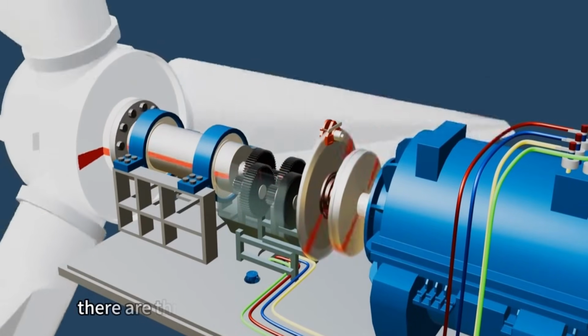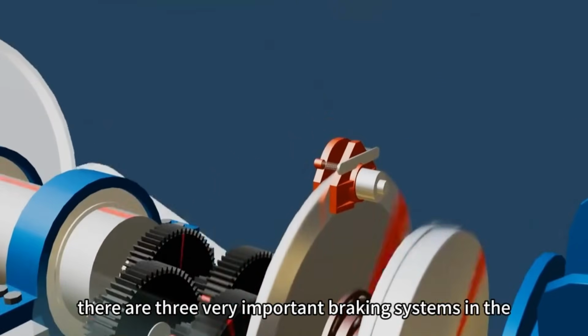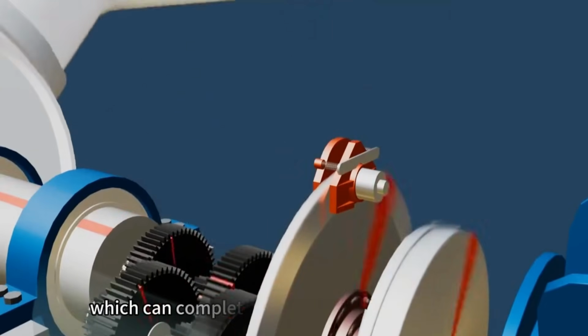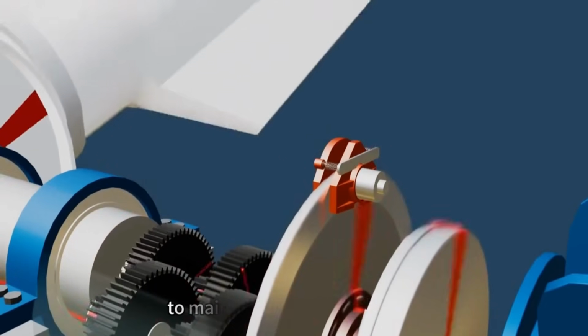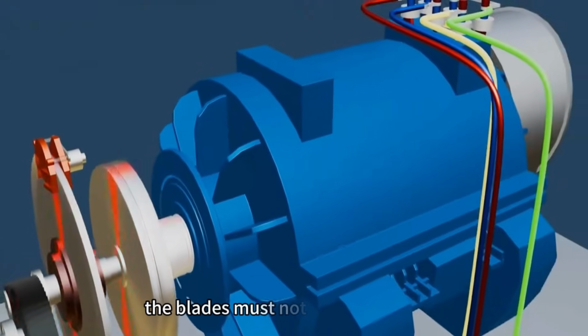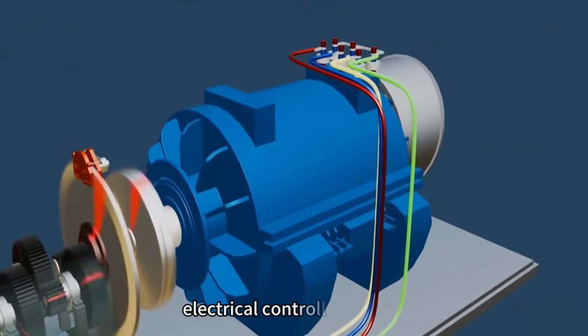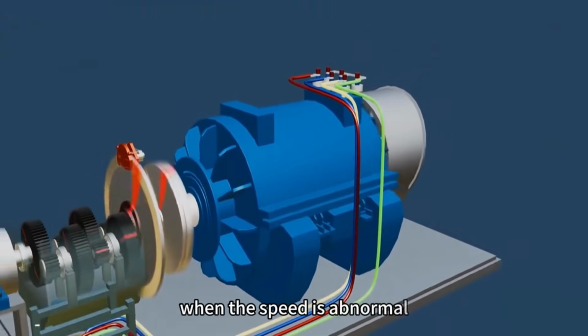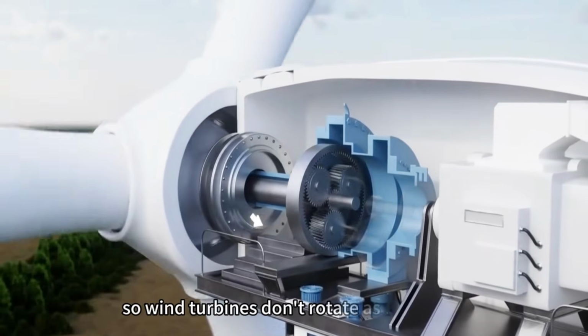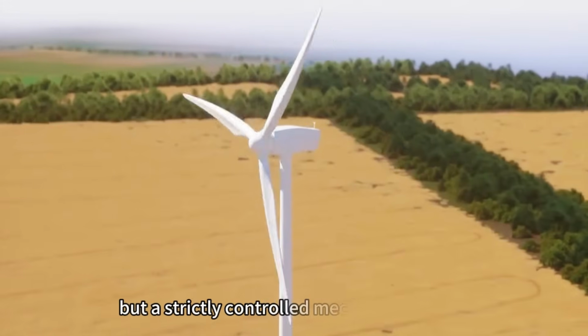Meanwhile, there are 3 very important braking systems in the cabin. Mechanical brakes, used for emergencies or maintenance, which can completely stop the entire wind turbine. Before maintenance personnel go up, the blades must not rotate randomly. Electrical controlled brakes: when the speed is abnormal, the system will automatically intervene and control, so wind turbines don't rotate as they want, but are a strictly controlled mechanical system.